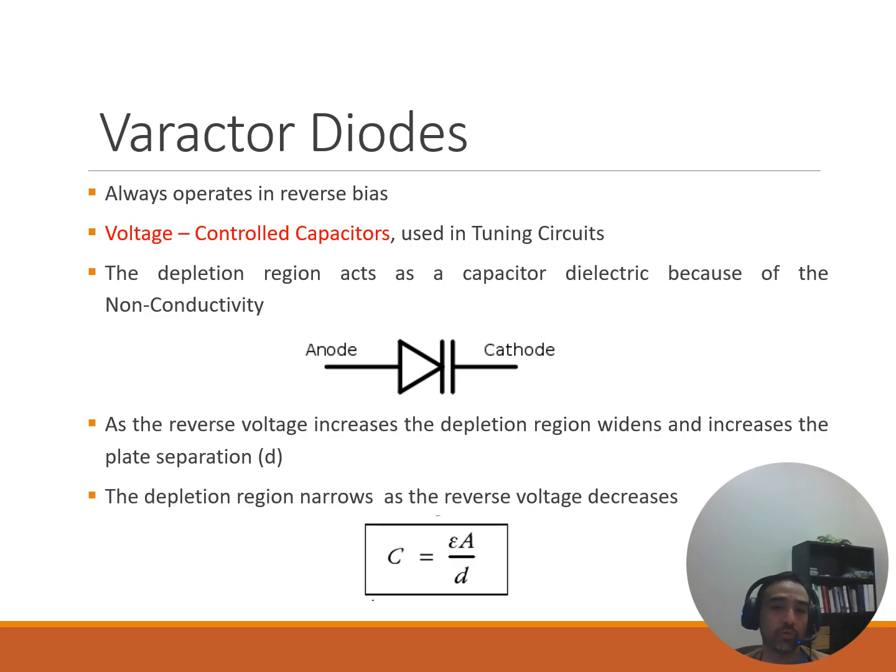When the reverse voltage, again, pushing electricity the wrong way, gets stronger, the depletion region inside the diode grows wider. Wider is probably a better word. It's like stretching a rubber band, and in the capacitor's case, it's similar to increasing the distance between the plates, the area where the energy is stored. So the bigger the distance means the capacitor can store more energy.